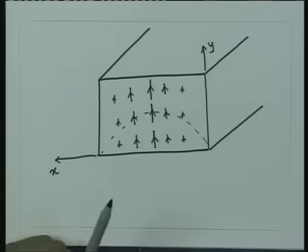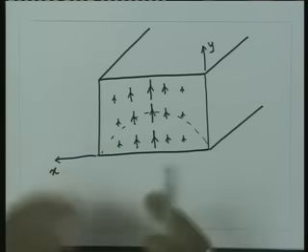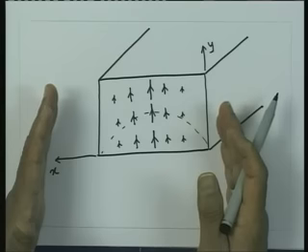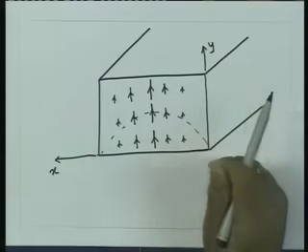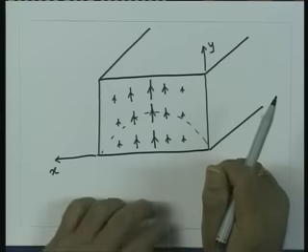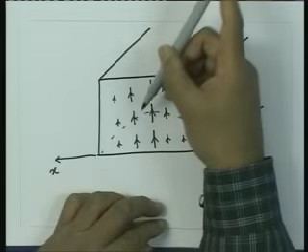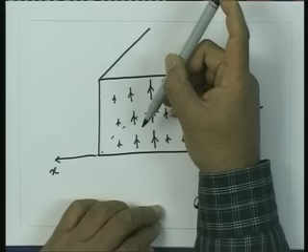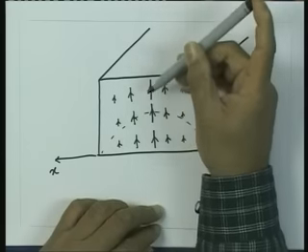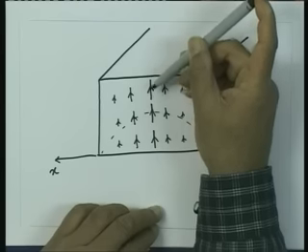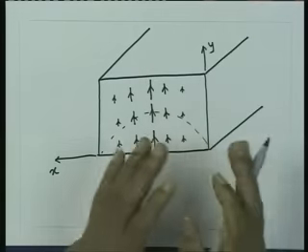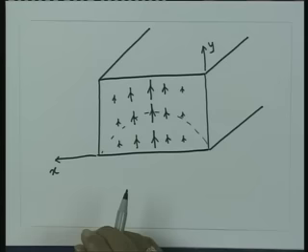So two things are required. Firstly, the size of the waveguide should be large enough so that the frequency is greater than the cutoff frequency for that mode. Secondly, the excitation mechanism should be such that the fields of the mode you want to excite match with the excitation.